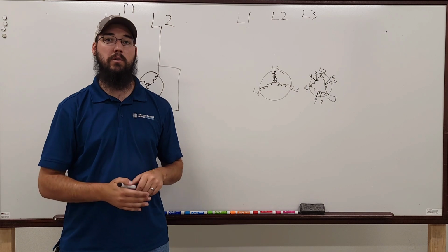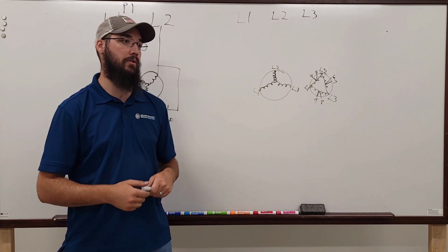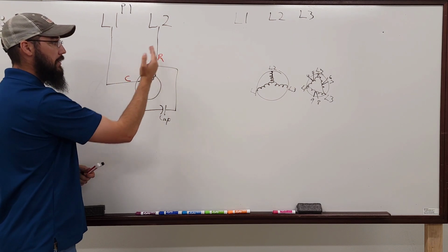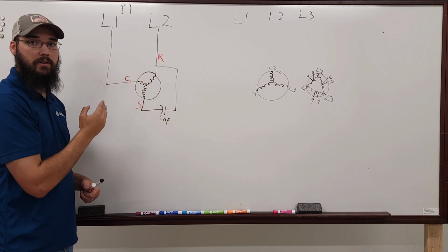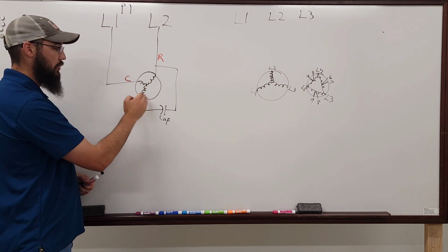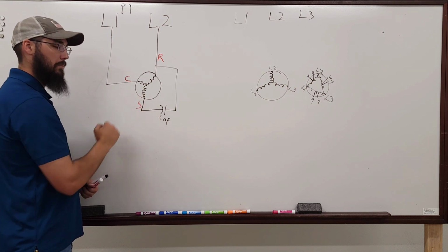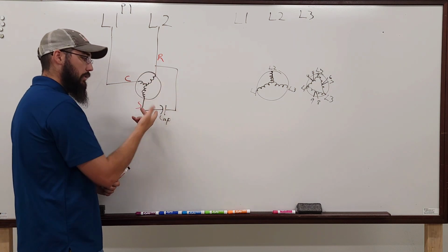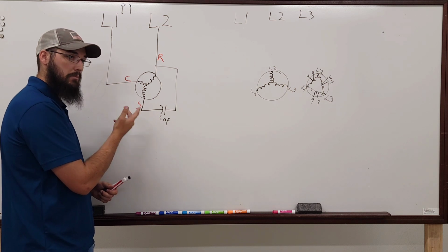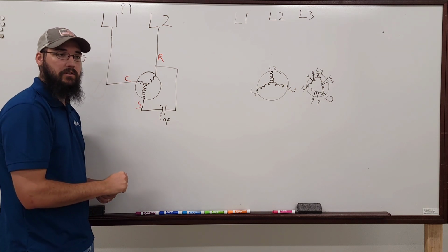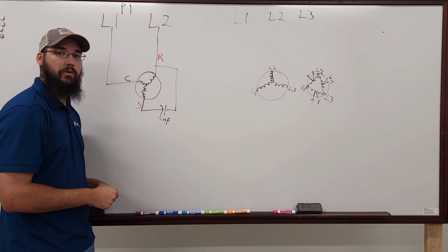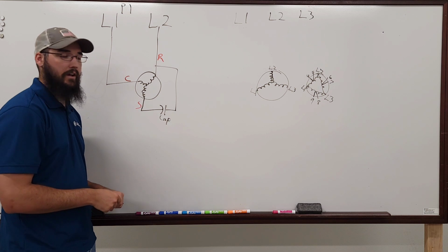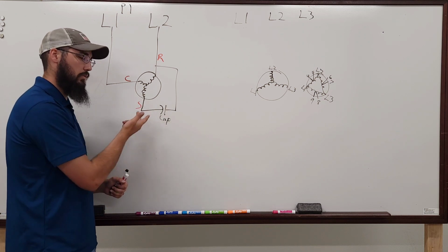Vast majority of your blower motors, tower fan motors, all of those are going to be a delta configuration. So your common and your run are the two that receive the power. The start is only pulling through the capacitor. And that's why if you do exactly what you were talking about and you switch those, the motor will run backwards, which I'm sad to say I run into more frequently than I really care to. It's way too often that I see these 2 wires switch.